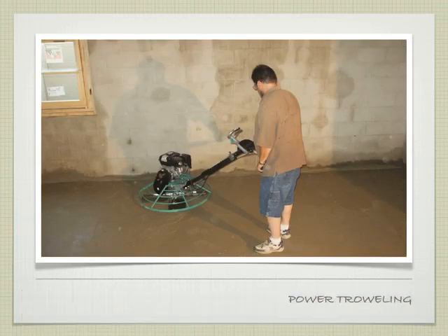The other thing that you could do, and I think I have a slide in a second, you've probably seen this in a parking garage, is they can do a stiff broom finish, where it has like a swirl pattern to it, a little bit of texture, so that it's not too slippery when it's wet. Same thing if you're outside on a concrete walkway or something like that. You don't want it to be perfectly smooth. They might put a little bit of extra water on the surface to expose the aggregate in the concrete to give it a little bit of texture. They might rub it with the broom. It's going to vary.